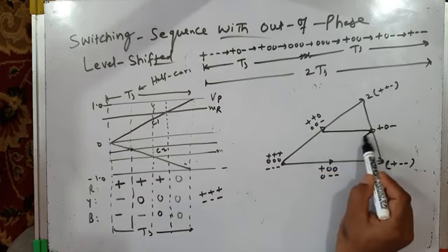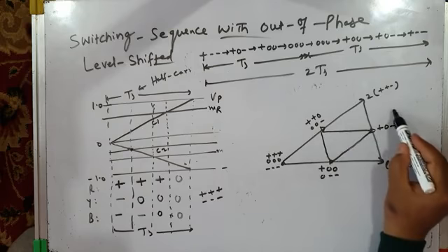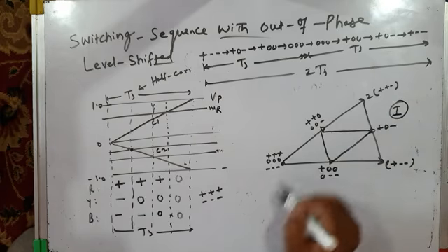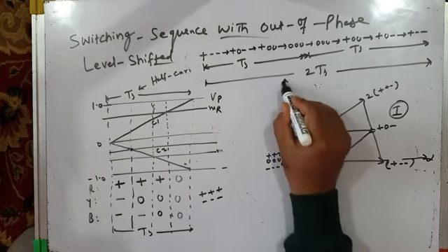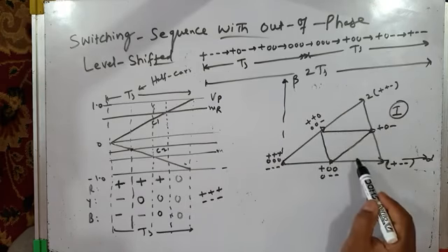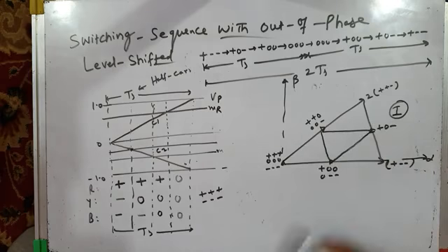Let me show you all the 4 regions. So this is region 1, region 2, region 3, region 4 in sector 1. ये आपका sector 1 space vector diagram. So this is alpha, and we already know this is beta axis. This is sector 1, and sector 1 we have divided into 4 small sub triangles which are called regions: region 1, region 2, region 3 and region 4.